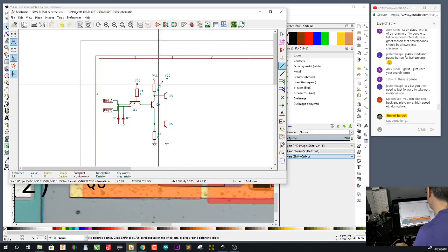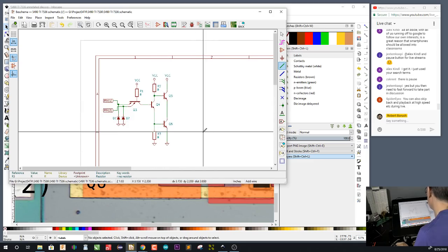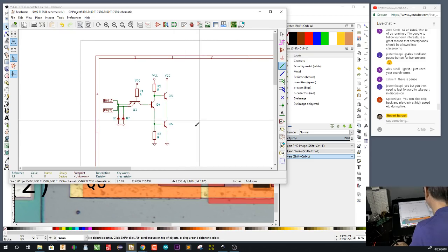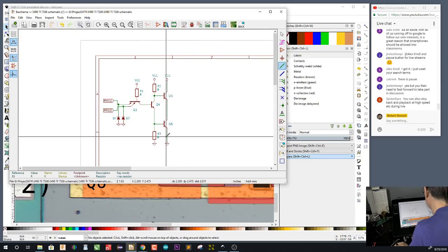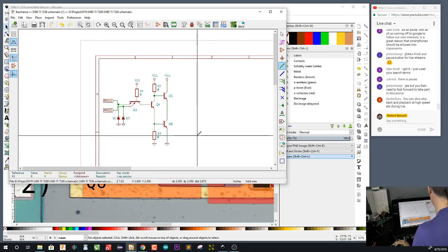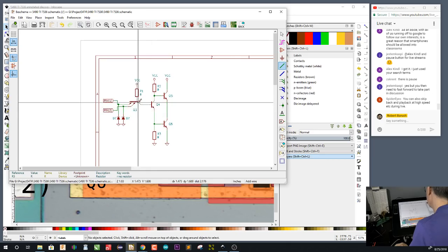Now this structure made out of a resistor, and then a transistor, and then a resistor, and then these two other transistors, that is a typical input conditioner. It's basically an inverter. And this is kind of like a push-pull situation. So we've got an AND gate followed by an inverter.